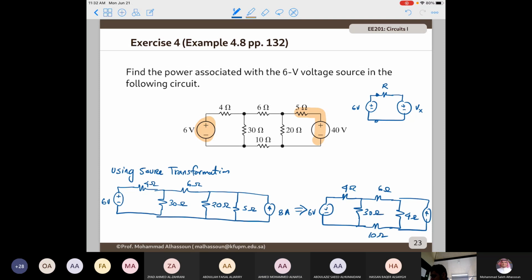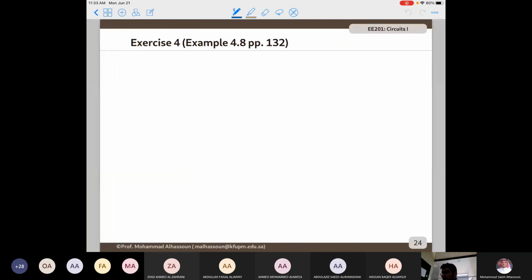Welcome. So this one is 8 ampere. Okay. So you can see here now what other source transformation we should use. From the current source, yes, so we have a current source in parallel with the 4 ohm resistor, so we can convert it into a voltage source in series with the 4 ohm resistor. So the value of the voltage source now is going to be 8 multiplied by 4, and the resistance will be in series.